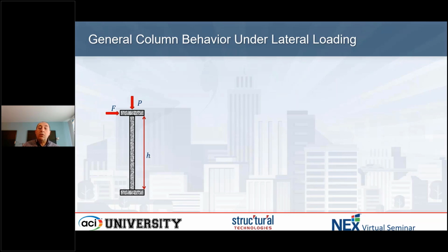And I think one thing I need to mention here is ductility is important for columns, and not only in moment-resistant frames, but also in frames with shear walls. Because even when you have shear walls, you're going to have lateral drift. And the existing columns need to go with the existing structure, be able to support the axial load without failing during the movement of the structure. So sometimes we have to still strengthen the columns and allow for lateral movement, even though we do not have a moment resisting frame. It's basically a lateral resisting system consisting of shear walls.